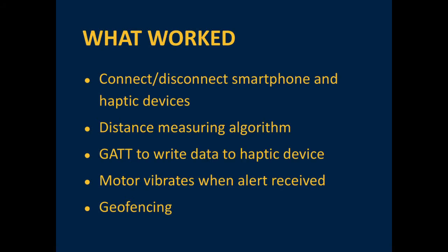We will now discuss the results and outcomes of our prototype implementation. Let's start with what we accomplished successfully. We were able to successfully connect and disconnect the smartphone with the haptic devices via BLE. After connecting, we successfully implemented an algorithm that was able to detect other haptic devices within 2 meters with a plus-minus 20 centimeter error radius.